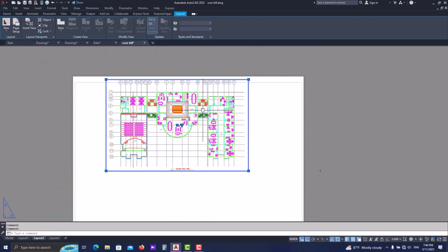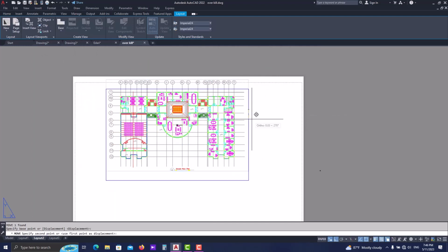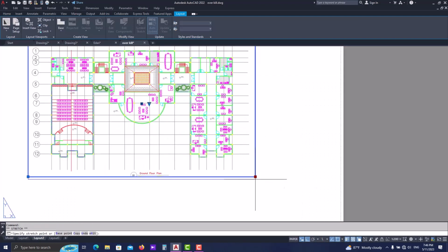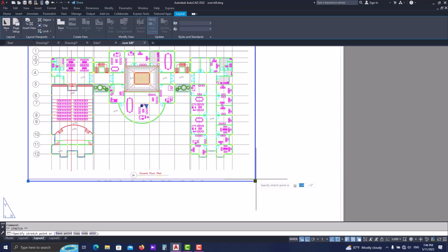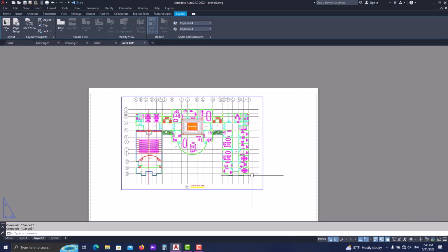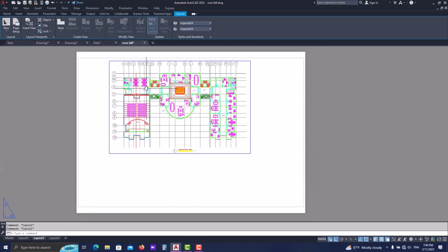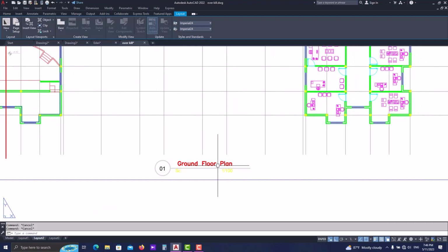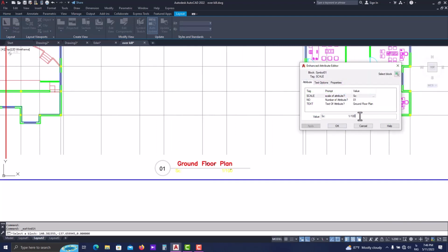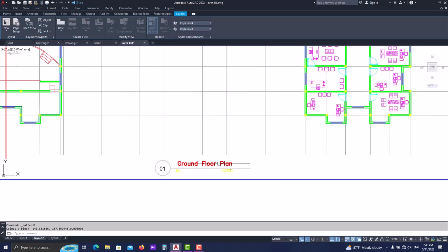Okay. And now that we modified our scale, we can do other things. For example, let's move it to another place like this. And then expand the frame a little bit more to display the tag completely. Okay, what else? Alright, we didn't modify the scale in the tag, so let's do a double click on it. Then in here, in Attribute Editor, change this to 1/200th, and okay.